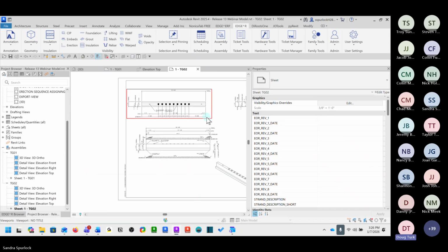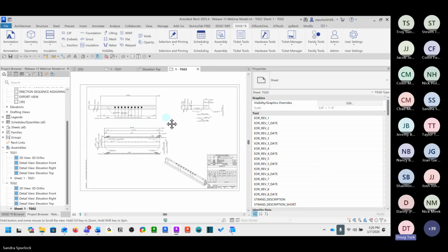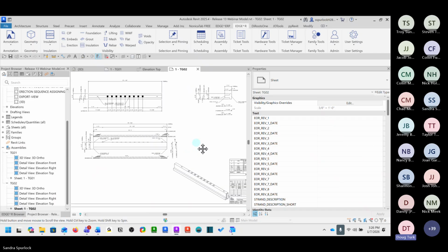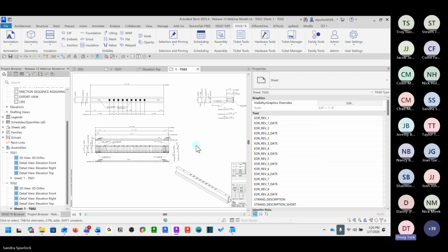Yeah, no, I agree. I think the majority of the auto ticket and clone ticket enhancements are quality of life formatting changes, most of which are addressing specific concerns and complaints that we've received over time for those tools. Specifically with the centerline dimensioning rather than edge dim lines, that addresses a problem a lot of people have had in the past with adjusting and changing and customizing the dimensions we generate.